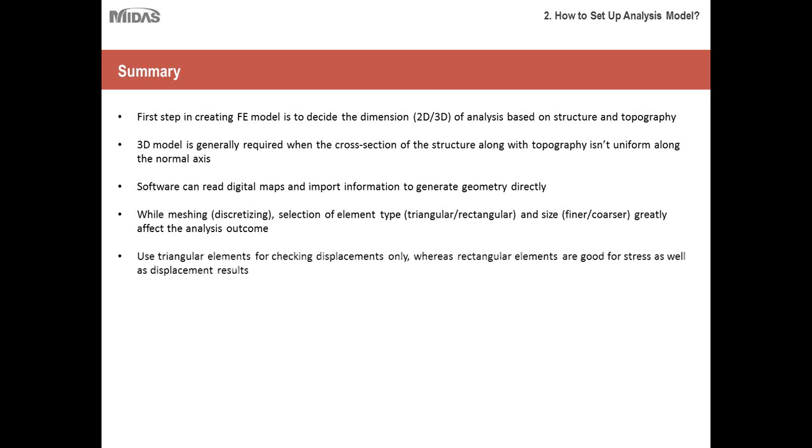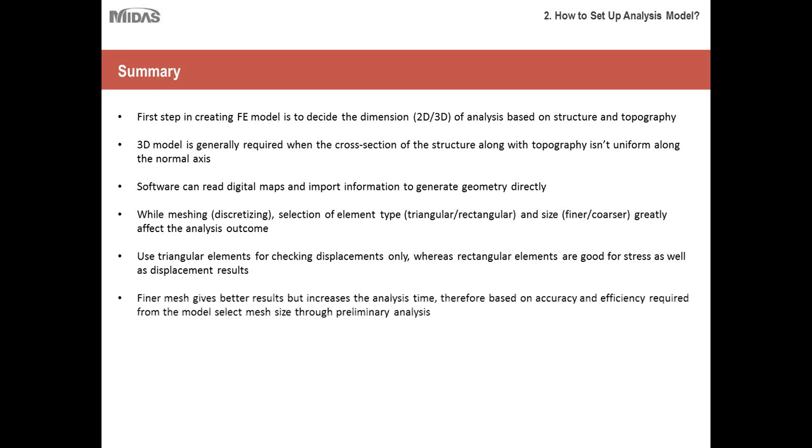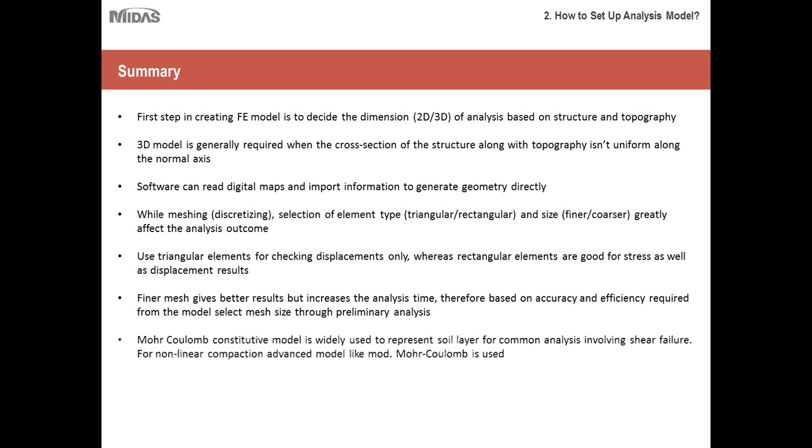Use triangular elements for checking displacement only, whereas rectangular elements are good for stress as well as displacement results. Finer mesh gives better result but increases the analysis time. So therefore, based on the accuracy and efficiency that is required from your model, select the mesh size through preliminary analysis. I hope this point is clear.